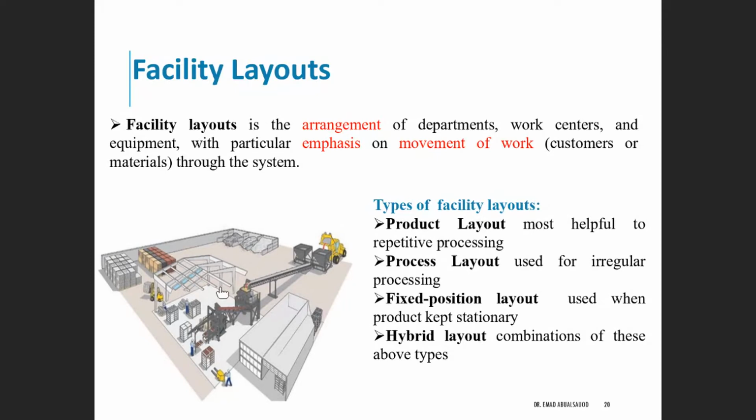you minimize the material waiting, and increase the flexibility for changes in the product design, also for future modification. If you would like to make any changes here, it will be easier since you designed it from the beginning considering the facility layout concept. Also increase the space utilization. When we say increase, it doesn't mean you will enlarge the area; the more accurate word is utilize, the optimal use of the space. Improve work method, reduce production cycle time, reducing the time spent in the production process.